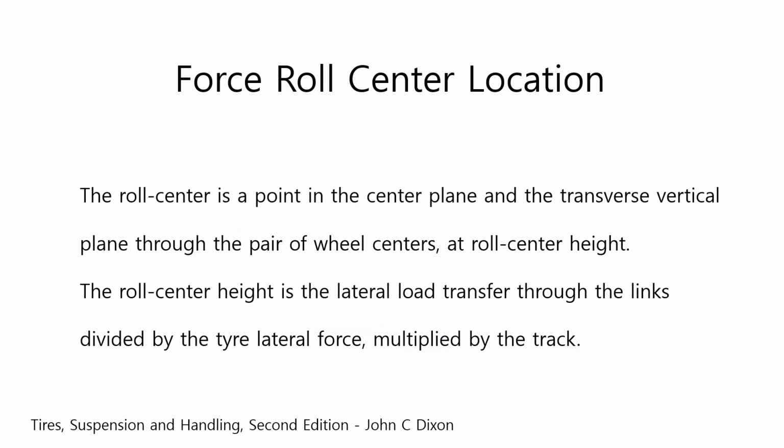Based on what we've discussed so far, we can define the location of the force roll center. The force roll center is determined by considering all nonlinear factors related to the tire and suspension components. These factors include rubber compliance, friction, and scrub, which continuously influence the suspension geometry depending on the magnitude of the lateral acceleration.